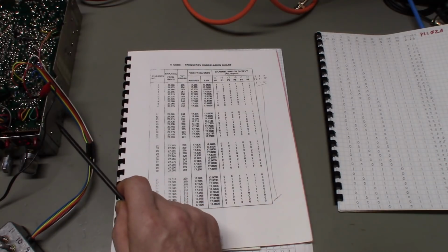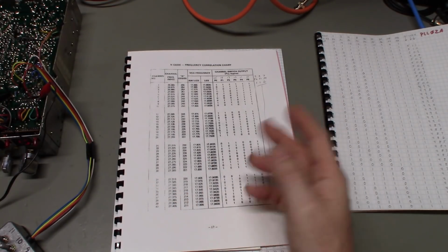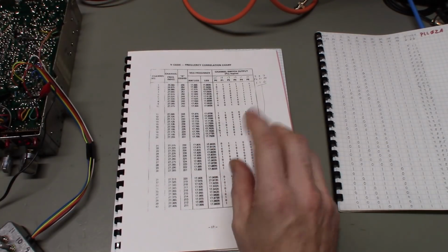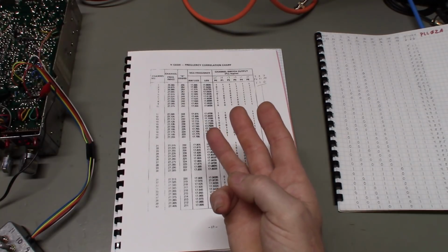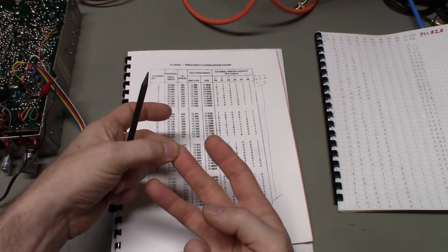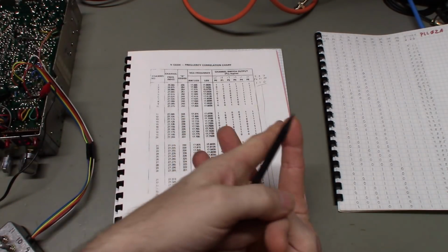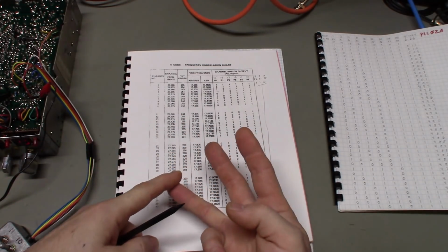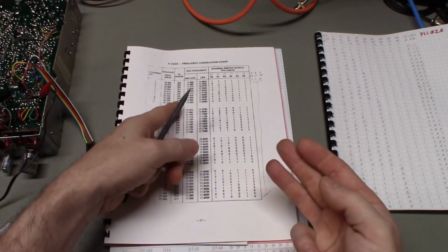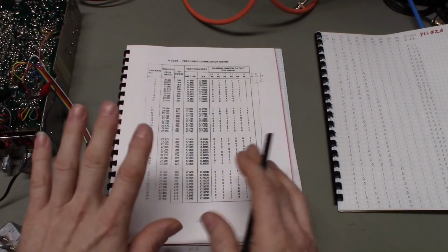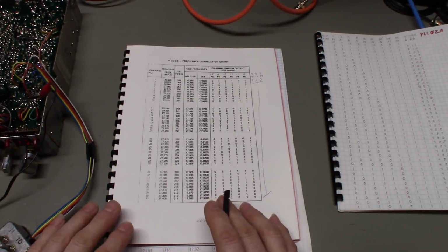You can change the crystal. So there were modification boards, Expo kits, that's what they were. The Expo kit usually came with a switch, and it had 3 crystal sockets on a little board. The center one would be empty, and then there would be 2 crystals on the outside sockets. That was for 40 additional channels up and 40 channels down. Then you took a crystal out of the radio, put it in that center socket, and ran some wires down. Never liked those things. Those wires have all kinds of inductance and capacitance.